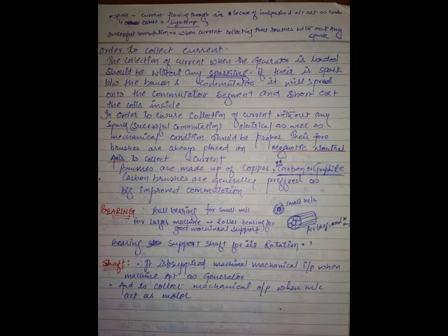So each pole, how much is it spanning? For example, if you take a 2-pole machine, and if there are S number of slots, for example 10 slots, what does pole pitch mean? Can we say 10 by 2?